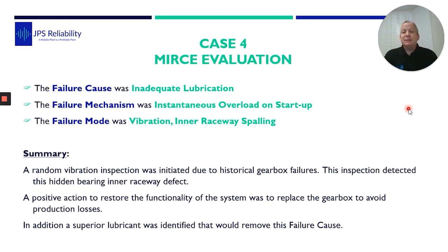But what is actually happening is, in the split second on startup, as the weights come around, at one point of that inner race, the highest loaded bit, there's not enough lubrication. So it's starting to really squeeze the bearing elements, and you're getting subsurface fatigue, cracking, and then spalling. So the failure cause is inadequate lubrication.